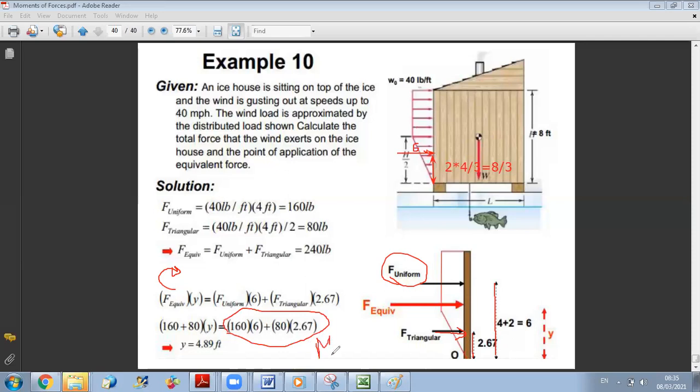Now, once you find the resulting moment about O, you can say that I can displace my force in a way to produce this moment. If I call this distance D, then of course here I should displace up. It should be up because your distributed load is all upward, so it is not logical for the equivalent force to be down. But you can do this for verification.